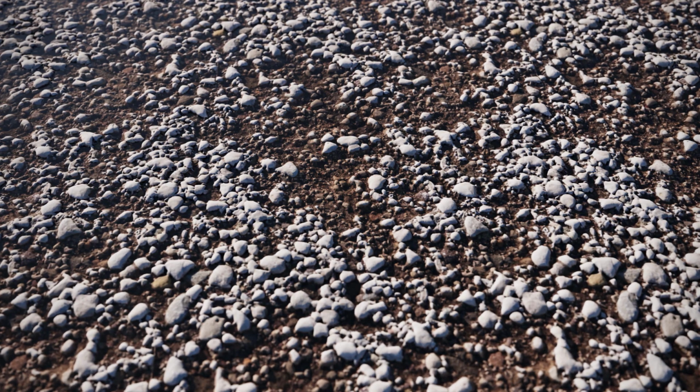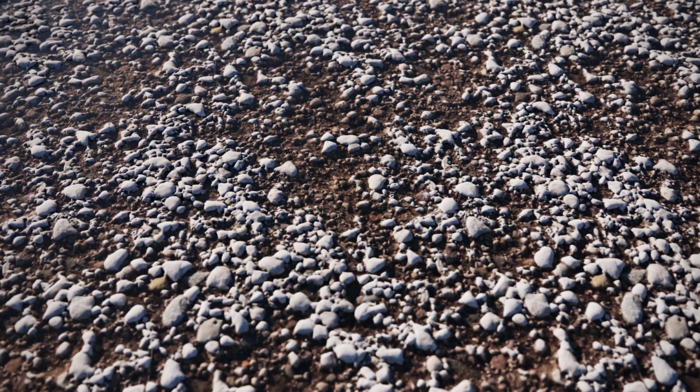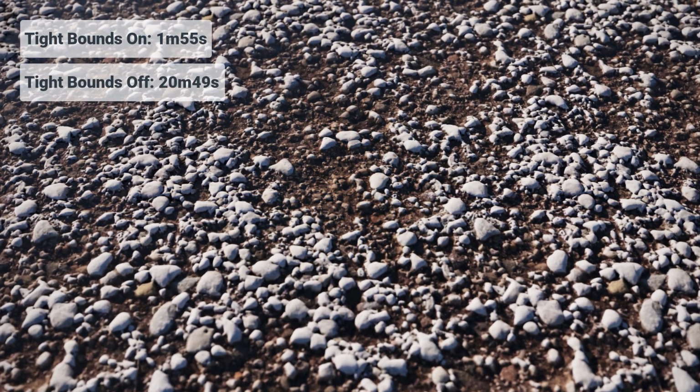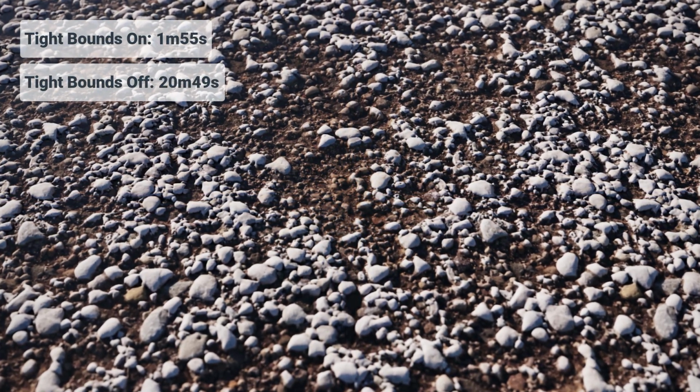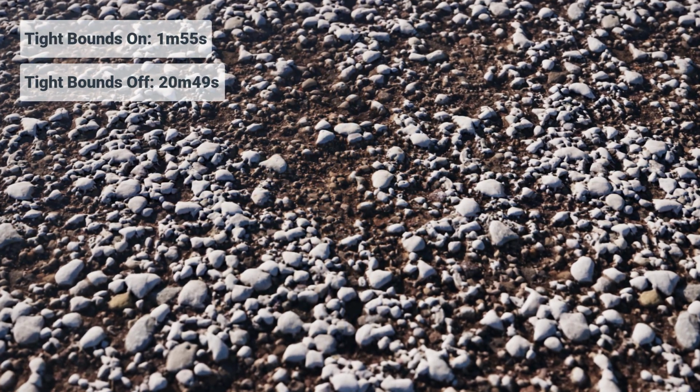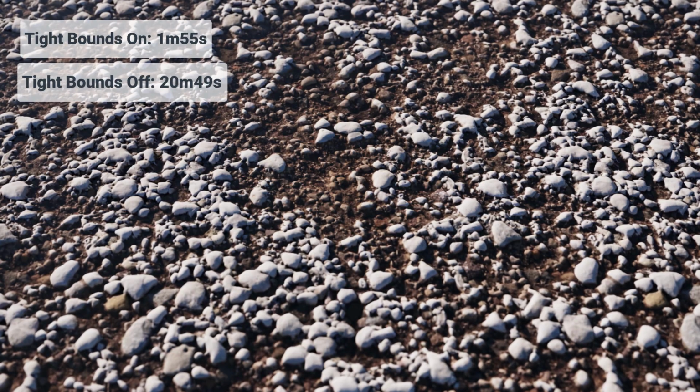Tight bounds help to render faster, but initialization will last longer. In this example, you can see the huge impact that tight bounds have over render time. The only situation where you might need to turn it off is when you run out of memory, since this is a memory-intensive process.